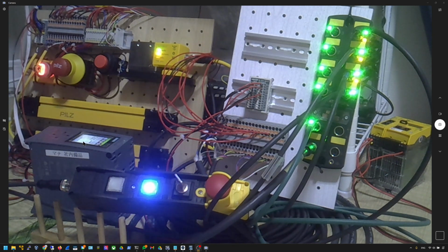So here you see this is my Siemens PLC, and here is my Schmersal Profisafe field box. Here I connect all the safety devices. For example, the emergency stop, the door lock, light curtain, and the control box interface. Some are connected to this terminal, and some directly use the M12 cable to connect to this Profisafe I/O box. The connections should be okay, so don't worry about errors, I'll show you step by step in the next part. So just a simple introduction, and then let's go.